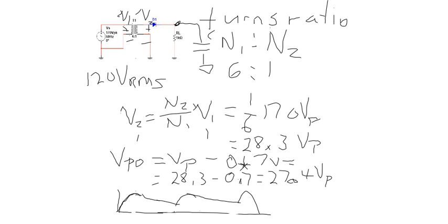Where that is a DC value, the peak voltage roughly, but we have something here, the change in voltage, we call the peak-to-peak ripple. And you can calculate that.